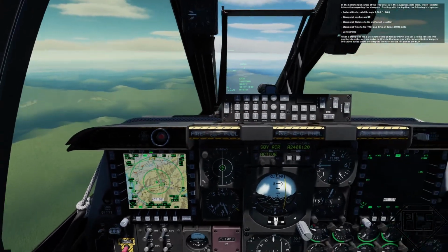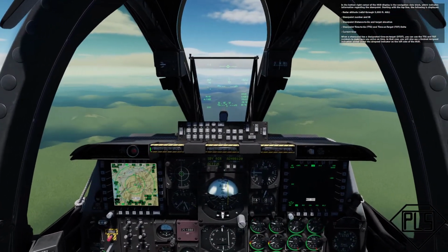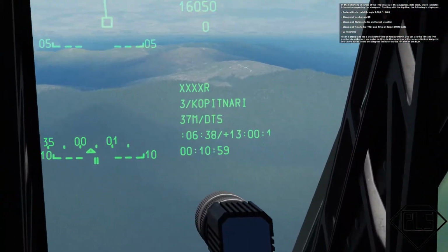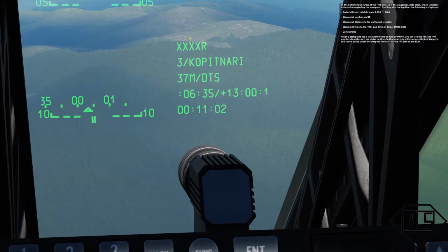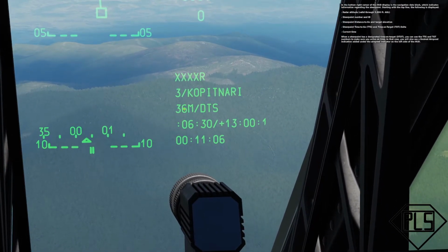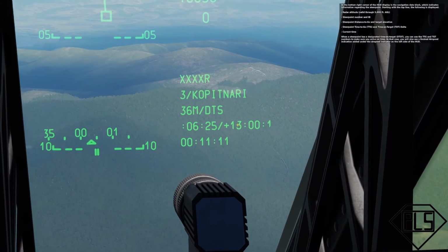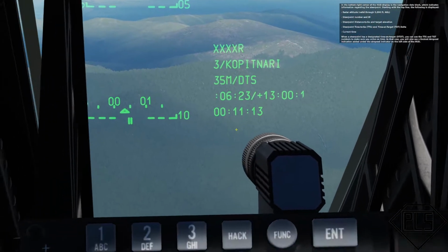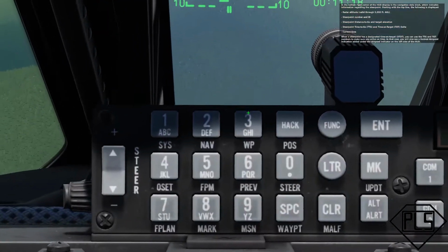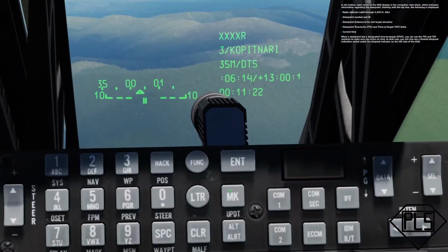In the bottom right corner of the HUD display is the navigation data block, which indicates information regarding the steer point. Starting with the top line, the following is displayed: radar altitude valid through 5,000 feet AGL, steer point number and ID, steer point distance to go and target elevation, steer point time to go TTG, and time on target TOT delta, also current time. When a steer point has a designated time on target, you can use the TTG and TOT numbers to make sure you arrive on time.